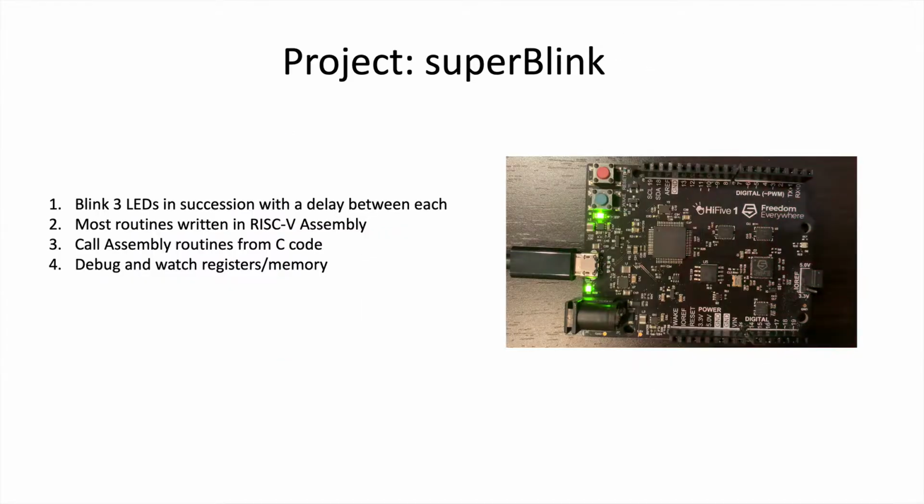So what we're going to do in this tutorial is we're going to build something called SuperBlink. And the reason why I call it SuperBlink is that in the microcontroller world, the equivalent of a Hello World application is blink the LED on your microcontroller. And so if you've done any kind of microcontroller development, you'll know that the first thing you do is try to blink the LED, and that just verifies that you've got a hardware connection that works and that your development environment also works. And the reason I call it SuperBlink is we're going to do a couple of things that go beyond the traditional Hello World or just blink the LED.